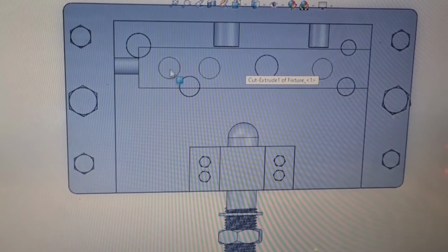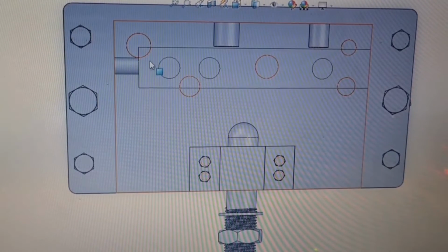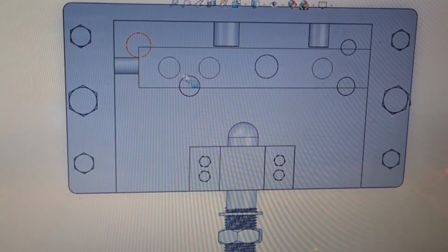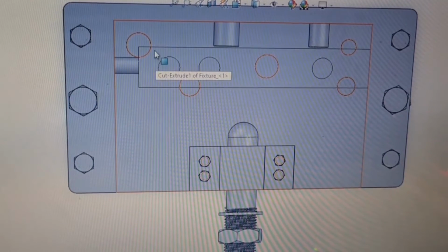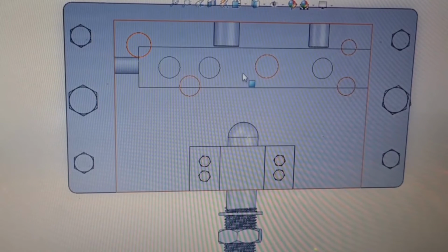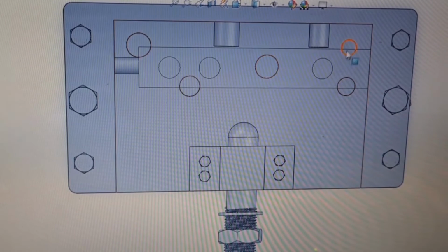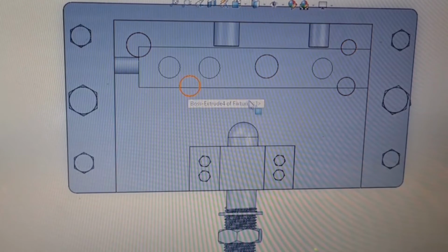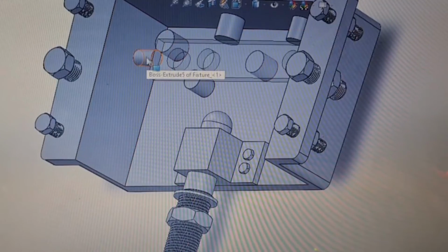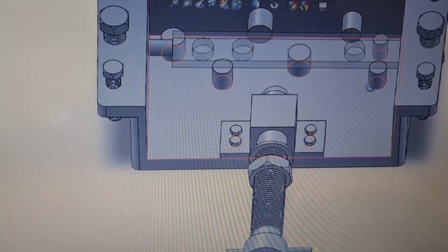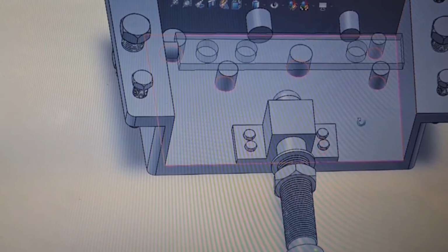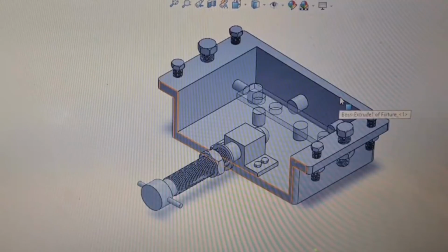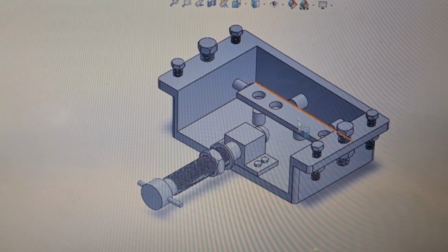The workpiece is on top of the pin locator. We use 5 different sizes of pin. When the drilling process starts, the workpiece will not move because it is held by 5 pins. At the left side of the fixture, we have 1 pin, and on the other side there is no pin because we fix the workpiece into the fixture.